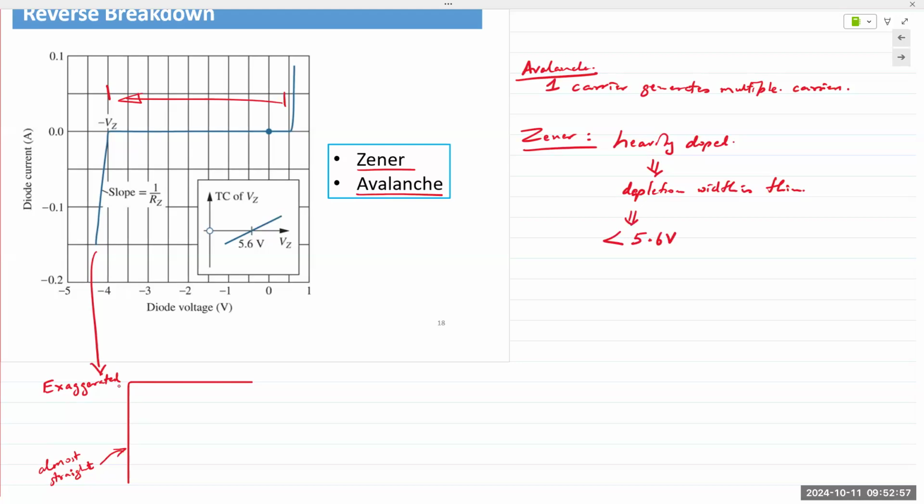We will perform a procedure in, I want to say lab 4, I believe, using Zener diodes. Now, we talked about reverse breakdown being due to 2 effects, avalanche and Zener. But by generally accepted practice over decades, whether it's Zener breakdown or avalanche breakdown, all of these are simply referred to as Zener breakdown. So you have Zener diodes ranging from a few volts, like 2 or 3 volts, all the way up to a few hundred volts. You can have Zener diodes even at 1,000 volts.